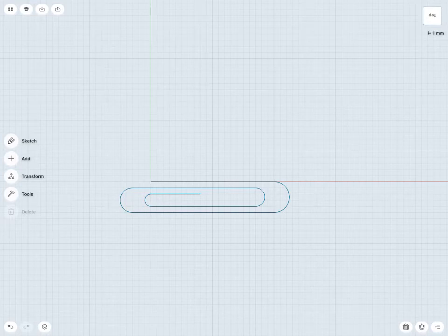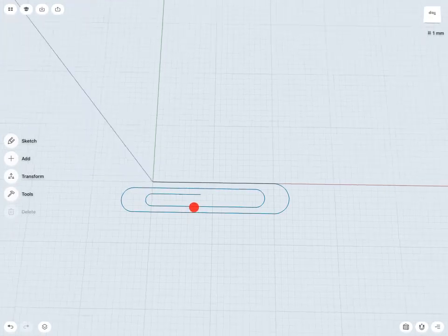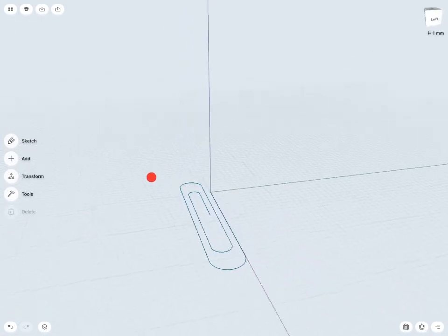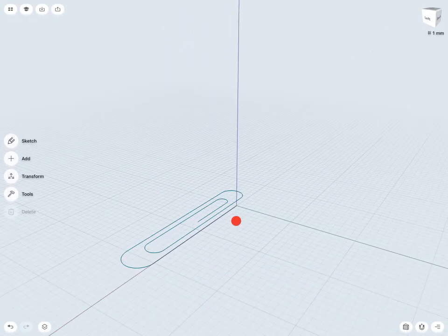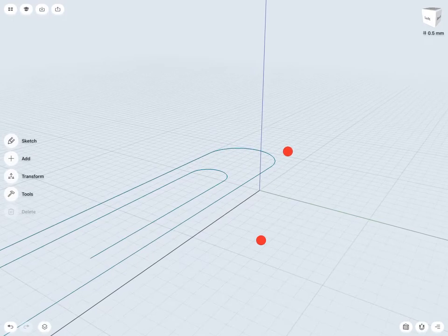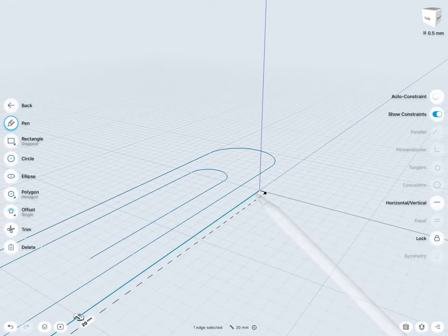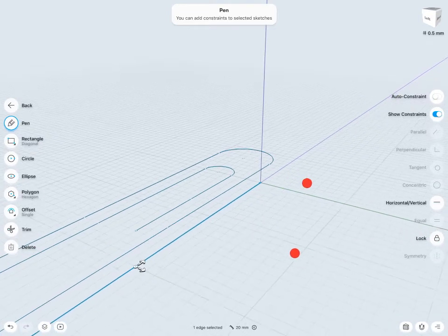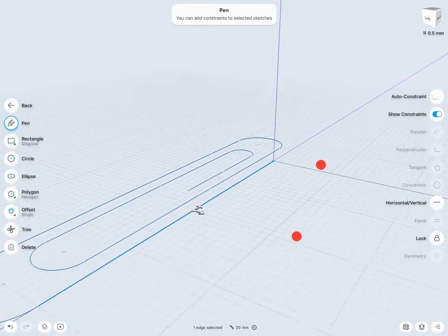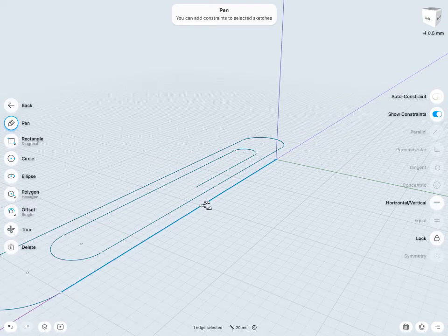And then essentially all I want to do is sweep a circular profile about this path. So what I'd like to do is now create another sketch just of a very simple circle. And I'd like that to probably start right at the beginning of my path. So in this case, probably right at that origin point would be a good place to sketch out that profile. And then I'm sweeping it or pushing it all the way around my path here.